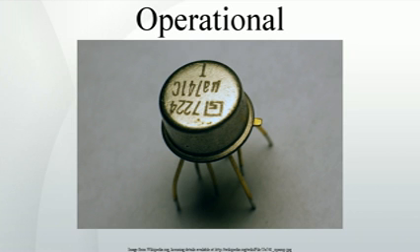These op-amps were effectively small circuit boards with packages such as edge connectors. They usually had hand-selected resistors in order to improve things such as voltage offset and drift. The P45, 1961, had a gain of 94 decibels and ran on ±15 V rails. It was intended to deal with signals in the range of ±10 V.